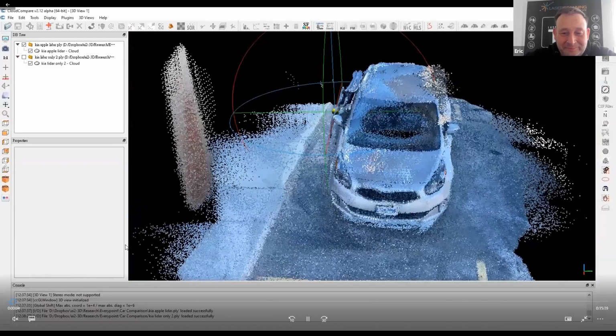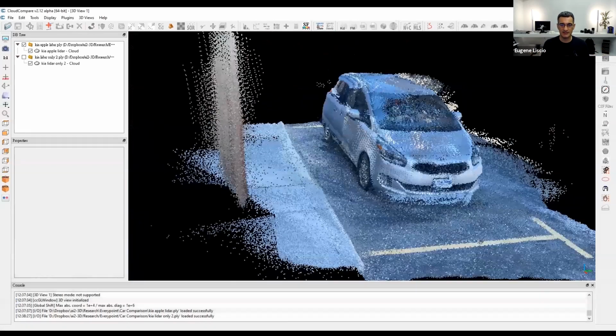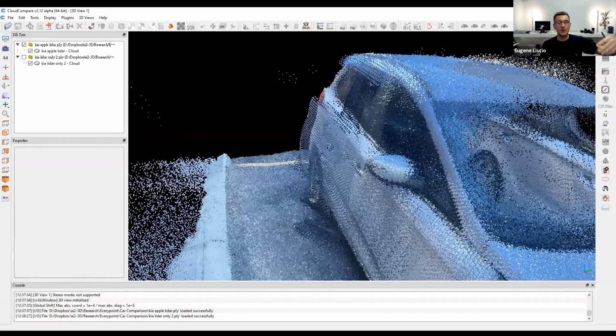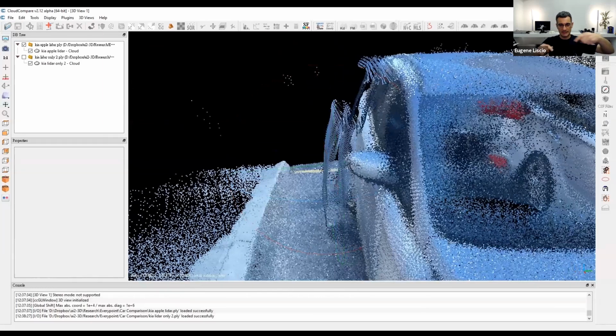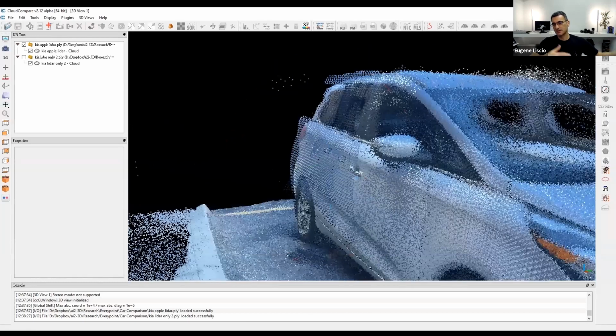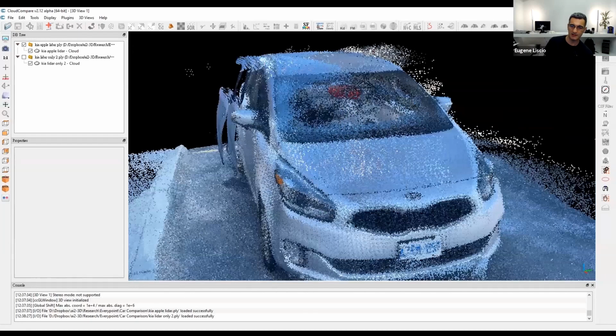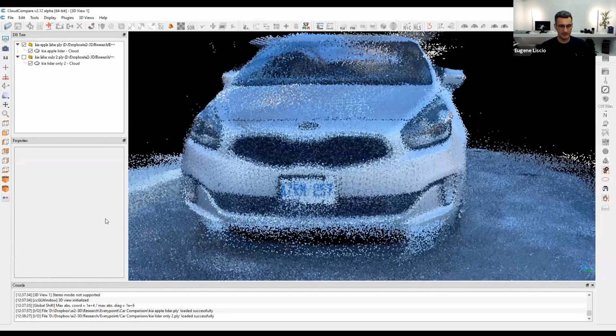This is just the LiDAR that's coming out of the app. You can see it's not great data. You'll see here, there's no loop closure, for example. You see it's double lines. It's just trying to put things together, but if it drifts, then it tries to go back on. You can't really recover or repair this sort of thing. So not that great, right?